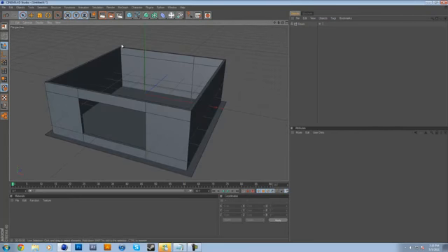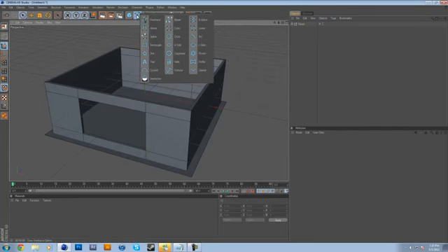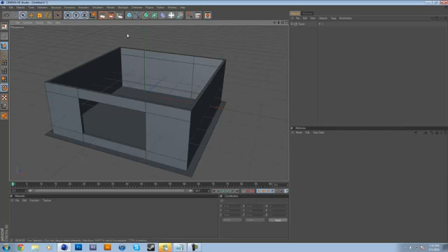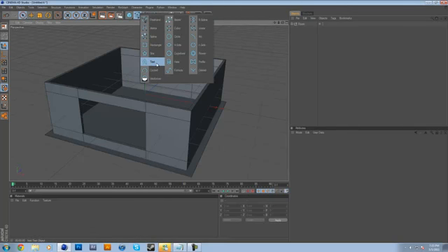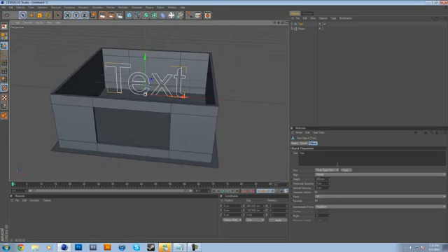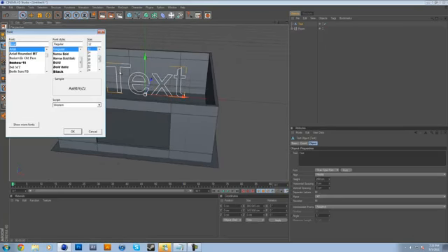Now I'm also just going to create our text now. I will show you how to do it through the splines, because normally I would use MoGraph to do it, but I'm aware that not everyone actually has access to MoGraph. So we'll use a spline. So come to our spline options here, just come to text, and I wanted to choose a very blocky sort of a text because that will allow more refraction and reflection and whatnot going on with the glass material. It'll just make it more effective rather than having a real thin, skinny sort of a font.